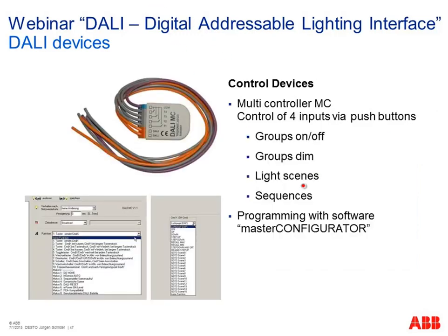A more intelligent device is the so-called multi-controller. Via the multi-controller we can also connect up to 4 different standard push buttons, and this device is configured via separate programming software like the Master Configurator, because we can do so many things. We can send group commands on, off, dim. We can call light scenes. We can start and stop sequences. Sequences are a kind of different scenes which will continue to be played. So a lot more things. That's why this device is programmed via separate software.